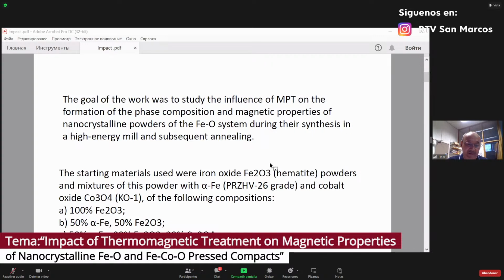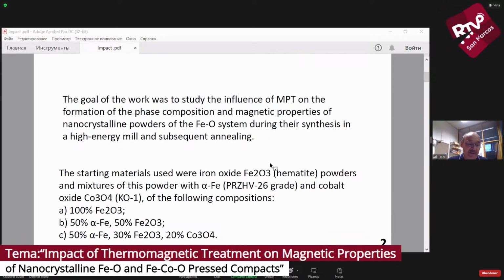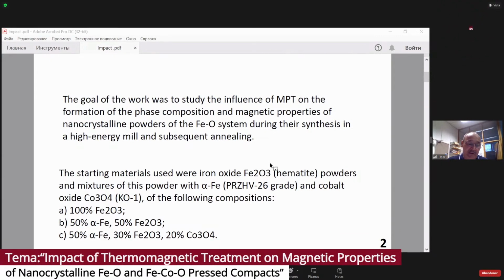It is believed that the cheapest materials for making permanent magnets are ferrites. The price level for barium and strontium compounds forces manufacturers of products using such magnets to look for cheaper analogs. An alternative could be nanocrystalline magnets based on iron-oxygen. They are cheap, but their magnetic properties are significantly lower than those of hexaferrite-based magnets.